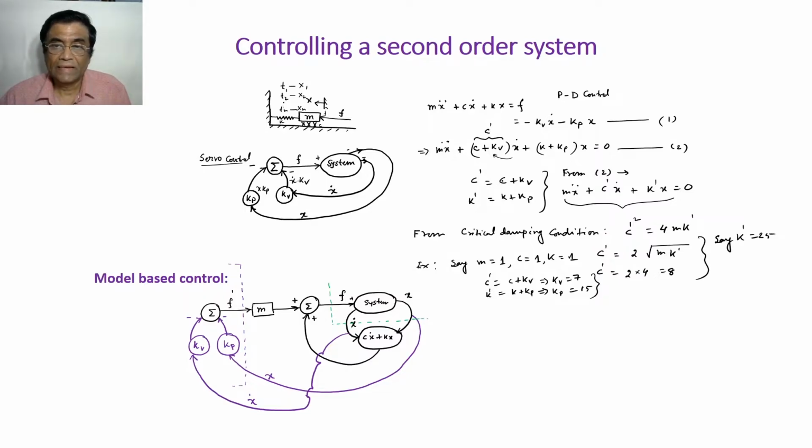As far as this mass spring damper system goes, no problem. But if you have different values of K, M, C, and you want to design a controller in modular form so that you can plug it out from one second order system and use the same controller on another, that is not going to happen, and that's a bad thing.